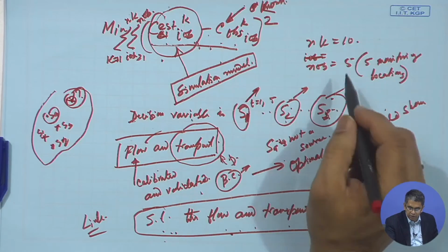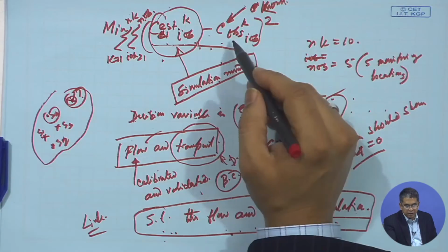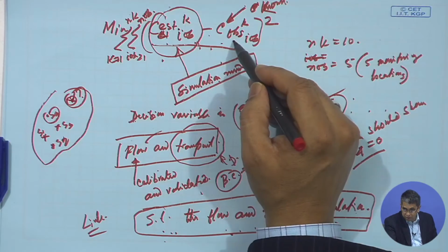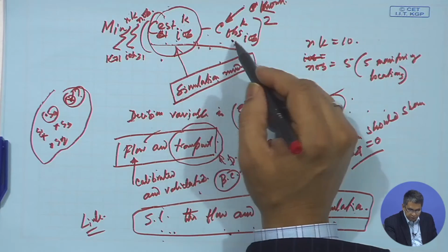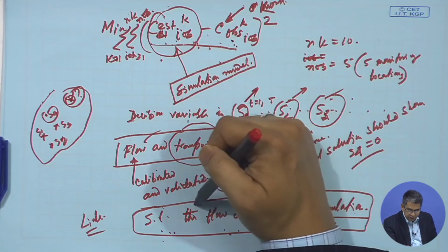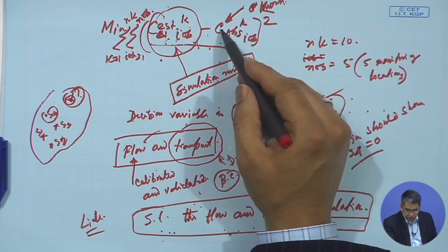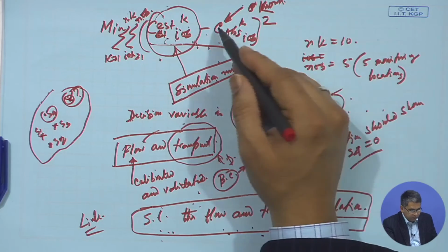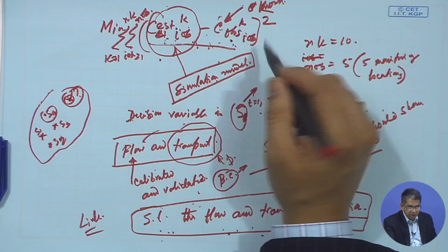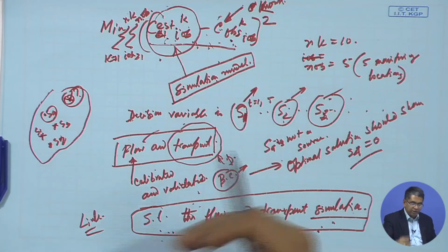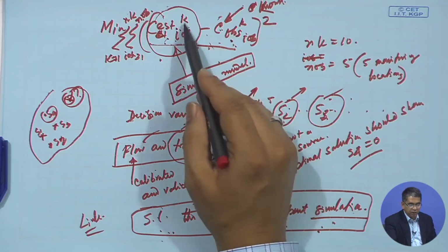It takes all these candidate values to the simulation model, finds out the resulting simulated or estimated values of the concentration, and sees what is the difference between this and the observed values, or measured values, actually measured in the field. Then it goes to the next iteration and sees whether it can further minimize this objective function value.